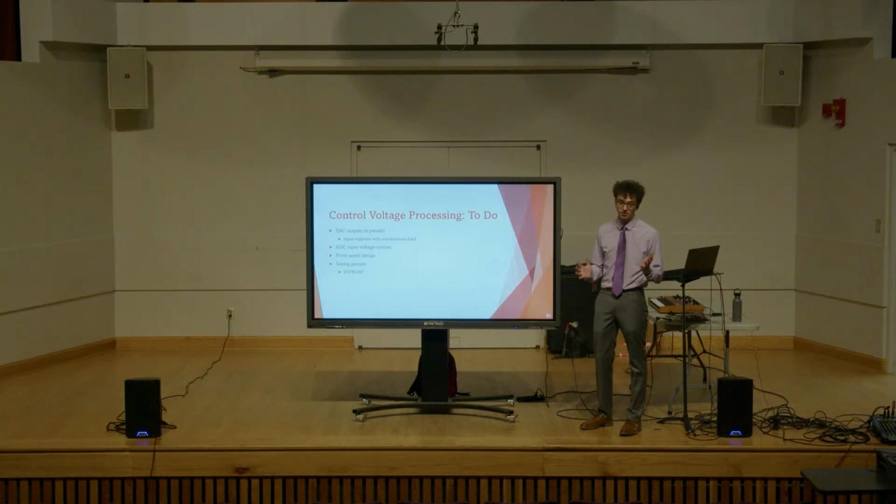I do have to come up with this front panel design once I've finished designing all these analog circuits and know what I have to control. And then preset saving, which is something I could realistically do now. The Pico has flash memory on it, which I could just start storing an array of data values to if I wanted to. I'm also considering an off-board EEPROM, which is an off-board, read-only memory which you can write to, overwrite previous values. But this is not that crazy an issue, and it's something that I can realistically just do now.